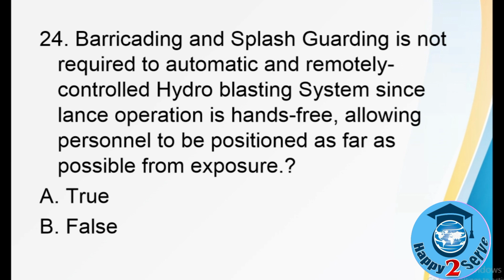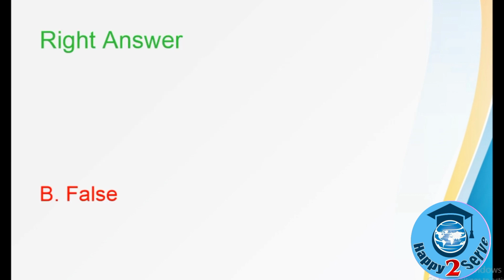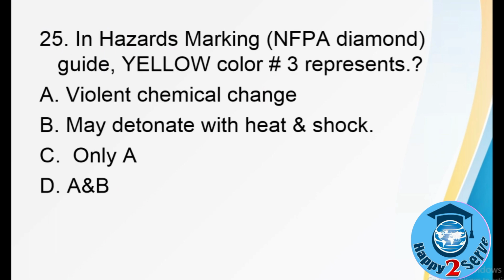24. Barricading and splash guarding is not required for automatic and remotely controlled hydro-blasting systems since the operation is hands-free, allowing personnel to be positioned as far as possible from exposure. A. True, B. False. Right answer: B. False.